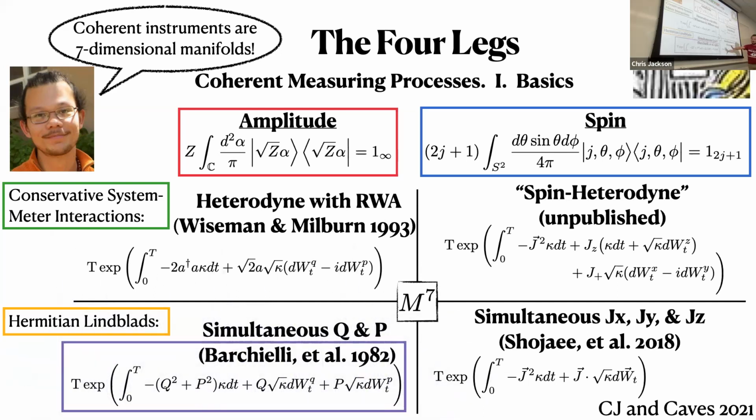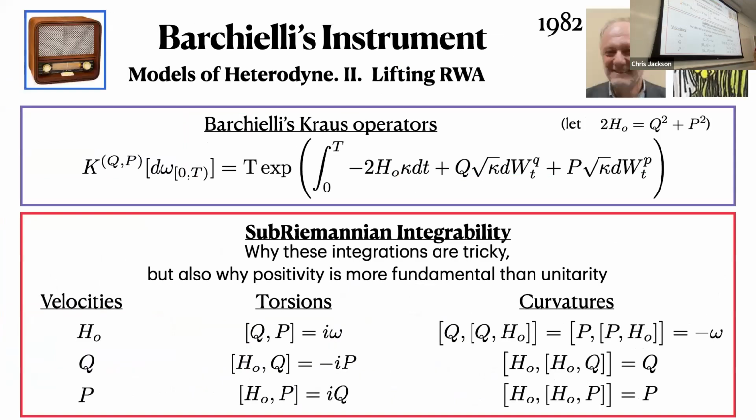Like I was telling you guys, this is the instrument I'm going to be talking in depth about. Give you a sense of what this differential instrument program looks like. Where do the 7 dimensions come from? If you know Baker-Campbell-Hausdorff, it means that if you start doing this kind of piling up problem, then what you have to worry about are Lie brackets. So to first order, you start generating motion in these 3 directions. I'm going to call them velocities, just to be geometric about it.